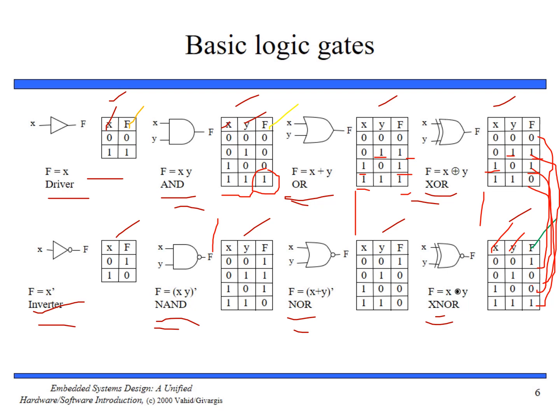So if you go to the previous slide, if we change 1 to 0 and ground 0 to 1, we can transform NAND to AND. Is that clear? I hope that it is clear. The NOR could be changed to OR similarly. Like in the top one, we can replace it with 0 and the bottom ground will be replaced with 1. We can have opposite functionality.